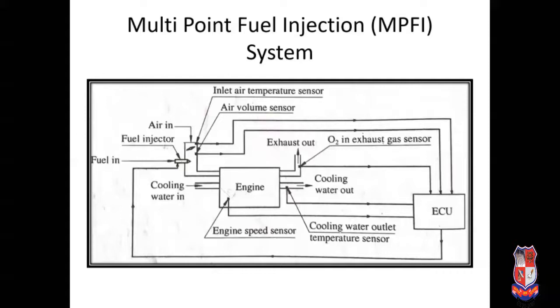Okay, in the port injection type, the injector is provided near the intake of the cylinder, and in the throttle body type, the air and fuel both mix up in one body, then after that the mixture is transferred to the individual cylinder.